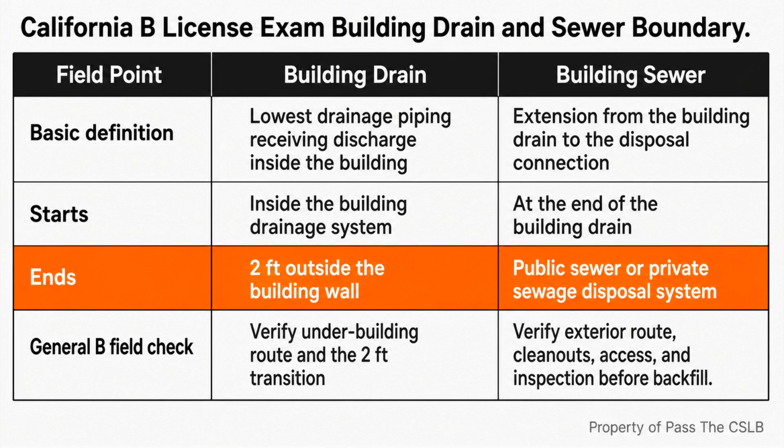The practical effect is straightforward. Gravity carries water and waste through the line. When a section becomes too flat, flow slows and solids can settle. That is why I check the bedding and the full run, not only the elevation at each end. The approved fall needs to continue through the trench without a belly, hump, or unsupported section that changes after backfill.